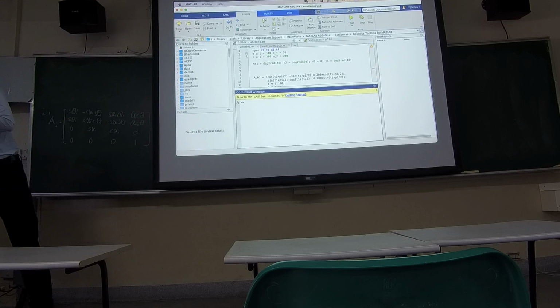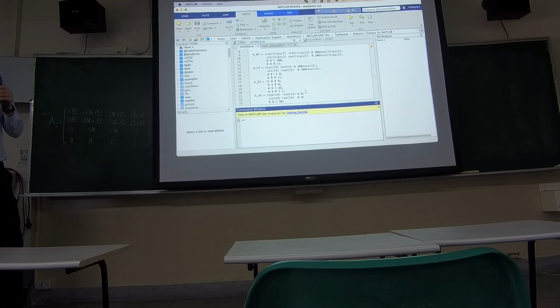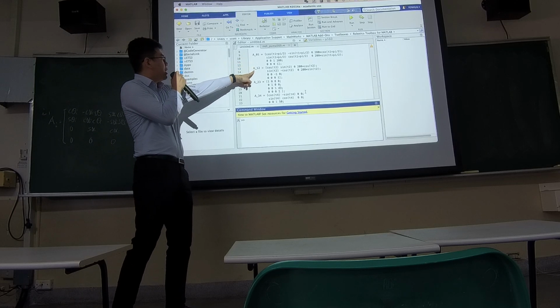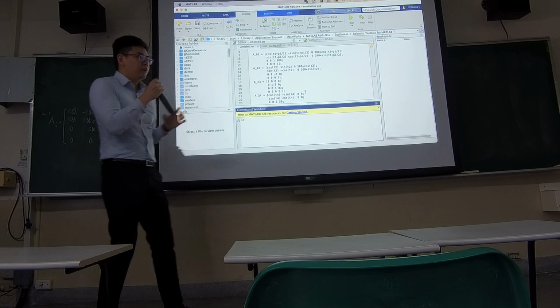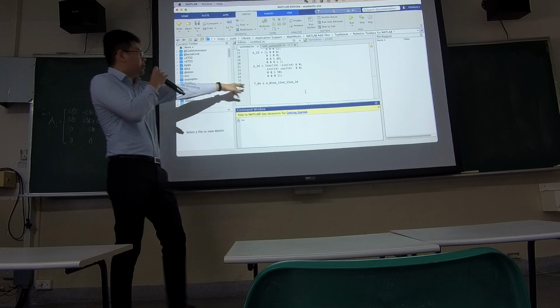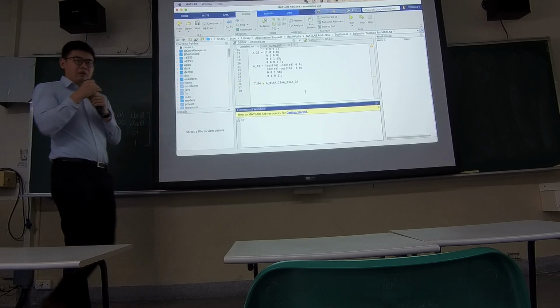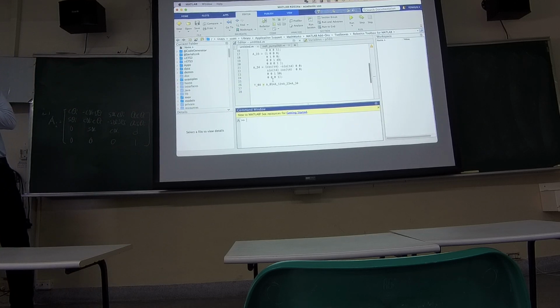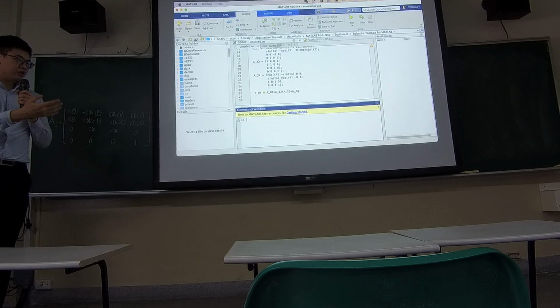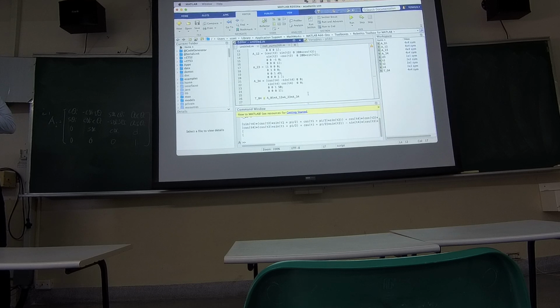And we just key in all the homogeneous matrices. This is A01, A12, A23, and A34, just like the program did. Then we just multiply all the homogeneous transform matrices together. Then we can get our transformation matrix for the end effector. So this is the solution of this forward kinematics.